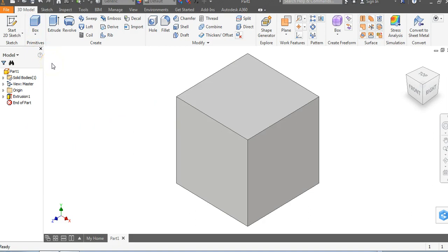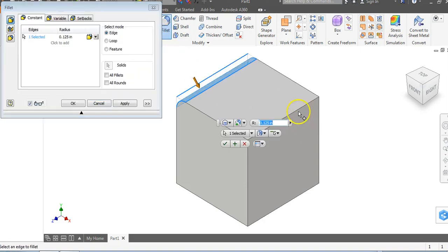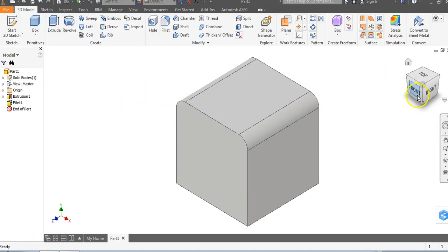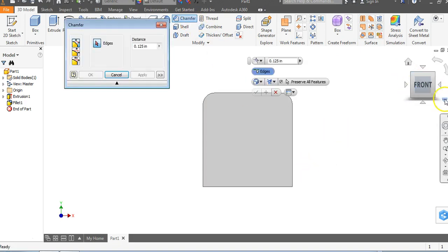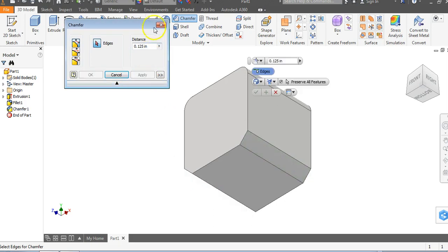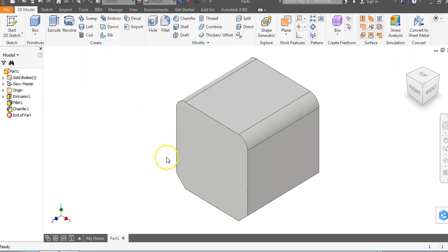If I know the 3 commands, I can go real quick: 1, tab, 1, enter, 1, enter. It's real fast. So again, if I'm giving an object to students and we're going to do any kind of subtractive modeling, where we take away mass from the object, we're going to fill it in, chamfer, I'll have them just go ahead and create a rectangular prism within the Primitives command, and then we can just kind of start taking things away from there. Makes it really fast to use.